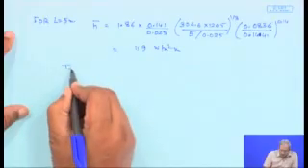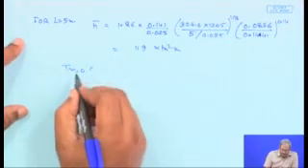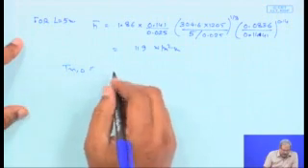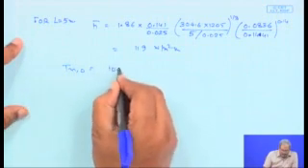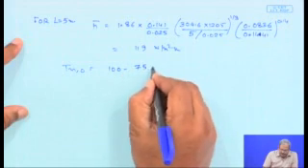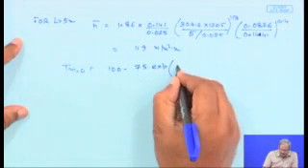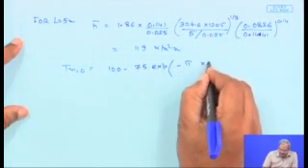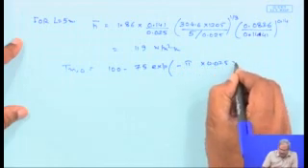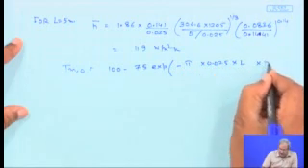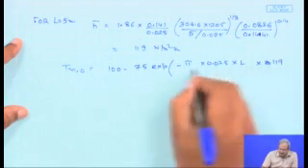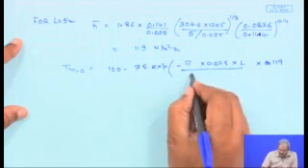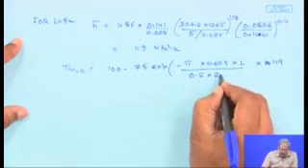So it's a straightforward use of the formula to obtain TMO for the case of 5 meters to be equal to 100 minus 75 exponential minus pi d L times H, which is 119, divided by m dot into Cp.